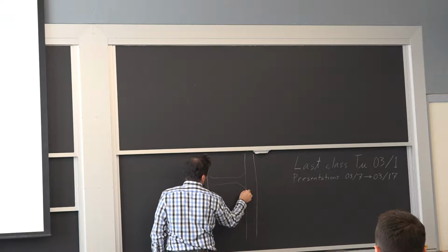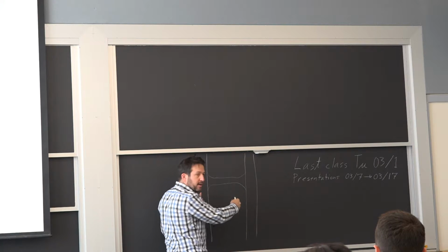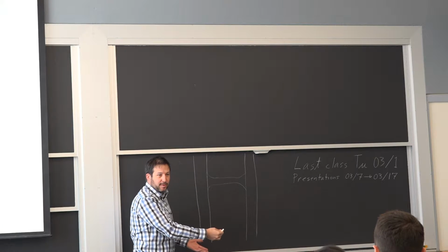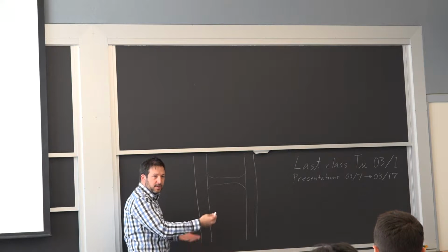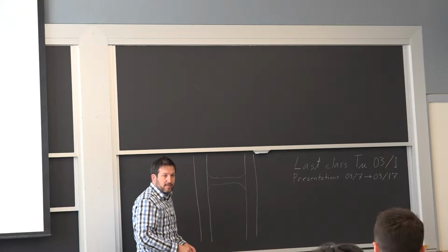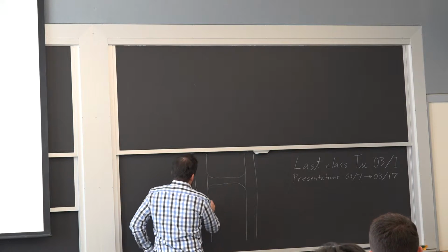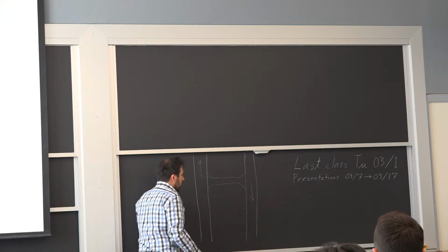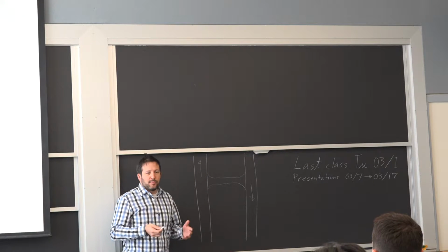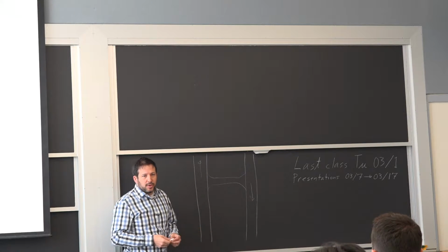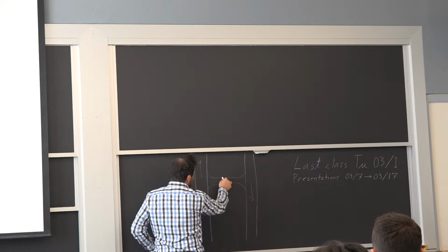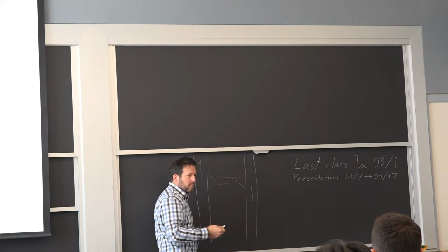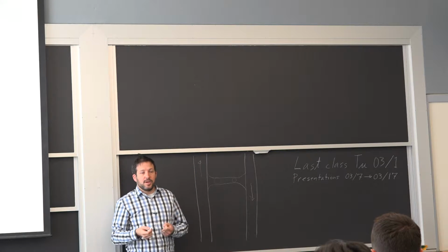What happens in a seismic event is it's not all going to lift at the same time because the earth, all the foundation, goes through a wave of movement. So if this column tries to go up, this one's trying to go down, you can't just completely prevent it. What you can do is have this member in the center or in these zones deform permanently and absorb energy.